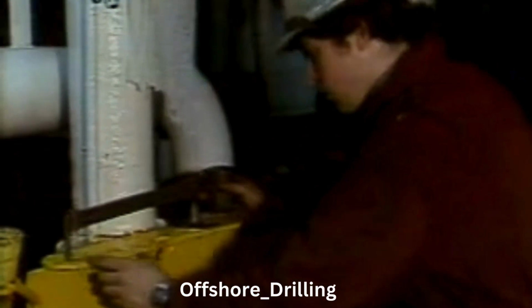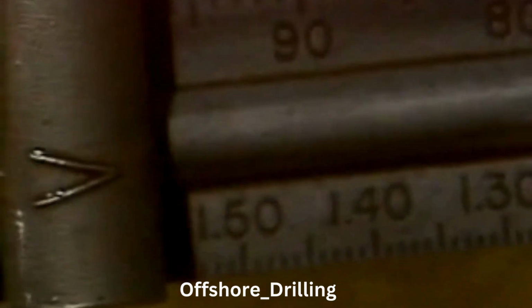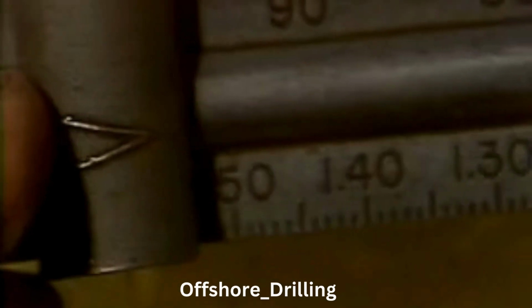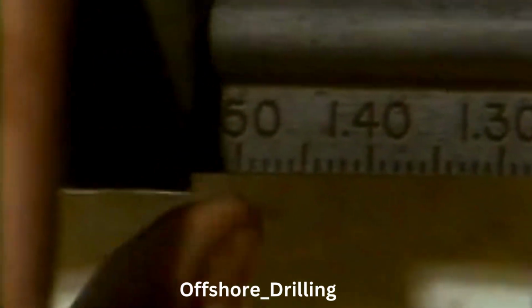Then dry it. Place the balance on the fulcrum. The knife edge fits into the grooved top section of the base on this particular unit. Slide the counterbalance until the bubble in the balance glass is centered. The density of the mud sample is read at the edge of the sliding weight nearest the base support.